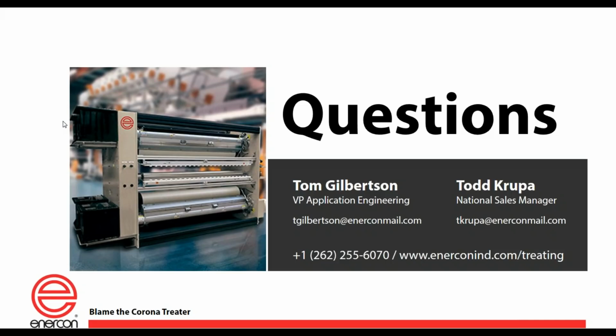So just be aware that it's not that you can't treat it, and it's not that you can't do a Dyne test, but the results you get are going to be even more variable than usual. In that case, I wouldn't lean too much on these Dyne tests. If that product is being printed, coated, or laminated, I would look more at wetting of the end result and adhesion of the end result, and focus on that along with the watt density number to guide yourself going forward.